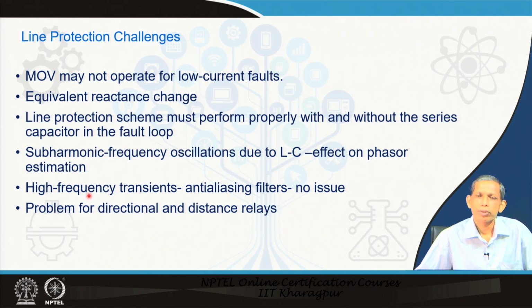Furthermore, because of this air gap and the MOV operations, high frequency transients will be introduced in the signal, but we have an anti-aliasing filter before the processing by the digital components. Therefore, they do not cause any issue to the numerical relay performance.